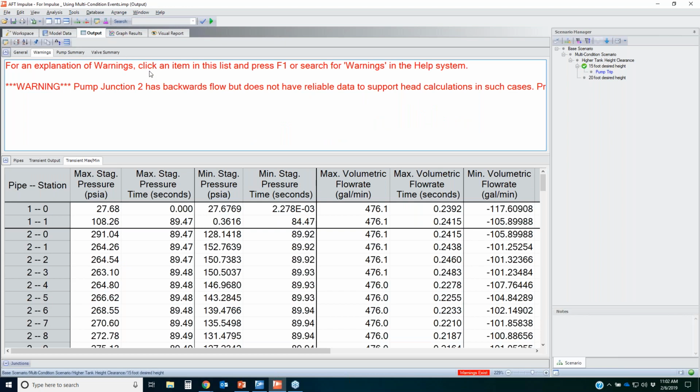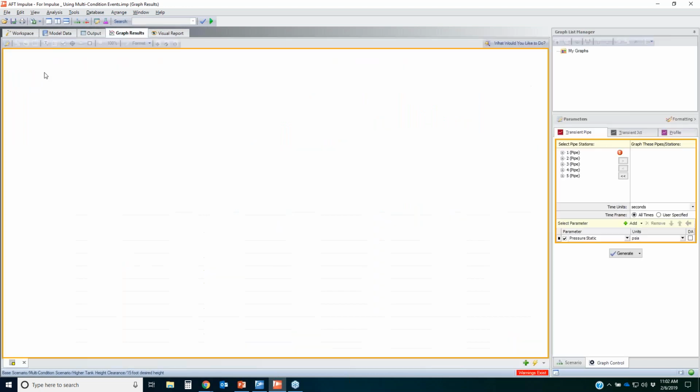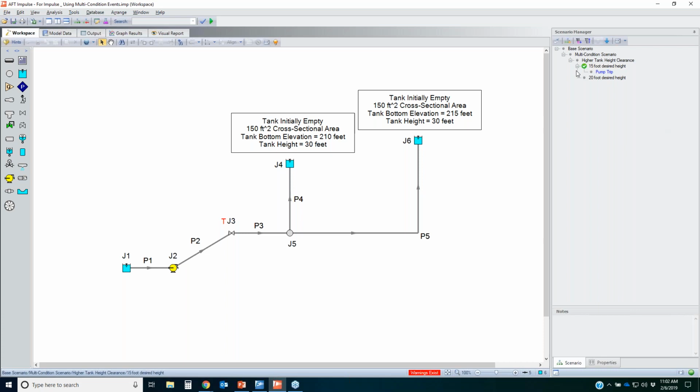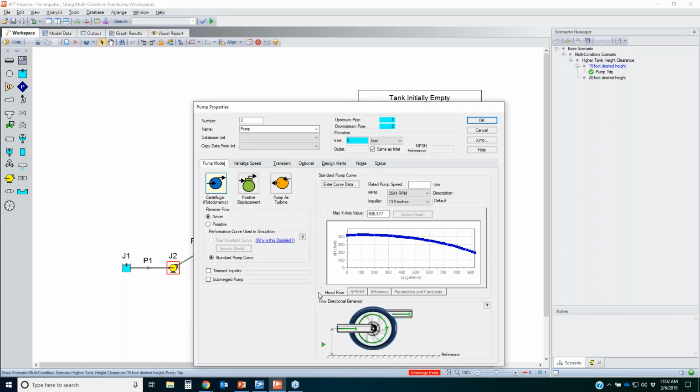So you're not going to have an accurate pump prediction in those circumstances. We're just going to be using the deadhead pump value at that time. So here, you'd want to include a 4-quadrant data set to better capture what would happen if you have reverse flow through the pump.